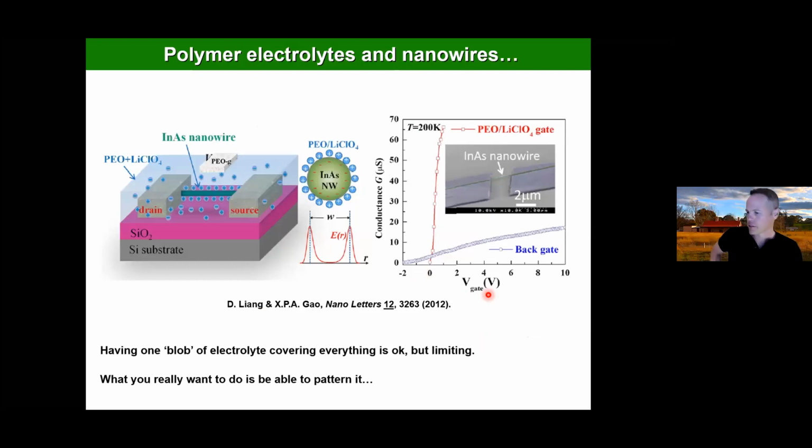So I came into this topic around 2012 or so, motivated by some work from Juan Gao's group at Case Western Reserve University in the US. They had this nice material system where they took an indium arsenide nanowire on a silicon oxide layer, and by doing a very short HF etch, they could dig out some space underneath that nanowire.